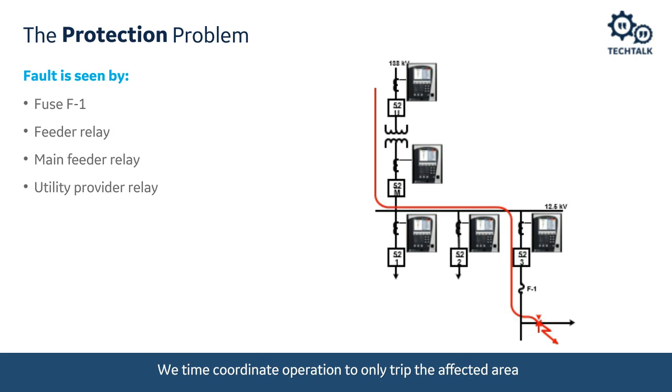And basically the way this thing operates, and even operates today, even if it's inside of a microprocessor-based relay, is that once the current that is measured by the relay gets above a pickup setting, the element operates with no intentional time delay.